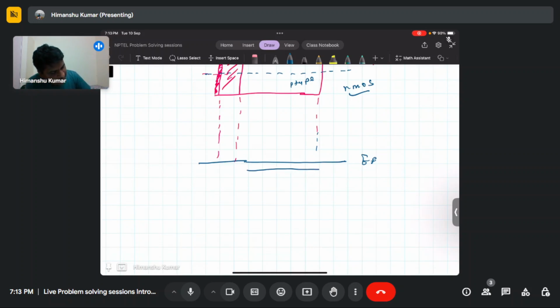Similarly you can draw the valence band and conduction band here. The oxide is a dissimilar material with a higher band gap, so it will have a band offset like this, and similarly here also. In the metal, the concept of band does not exist, because it follows normal Fermi statistics, and you can define the characteristic just by drawing the Fermi level. So this is the band diagram.